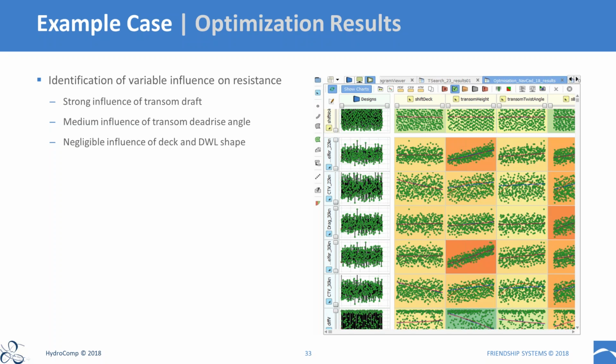This is simply based on the choice that was made here. Of course, you can set up a variable for the midship coefficient, either by defining some deformations that are applied to the midship area, as we did here in this case, or if you have a parametric model of the vessel, then one of the parameters that define the geometry can be the midship parameter values. So I think that's simply the choice that was made here.